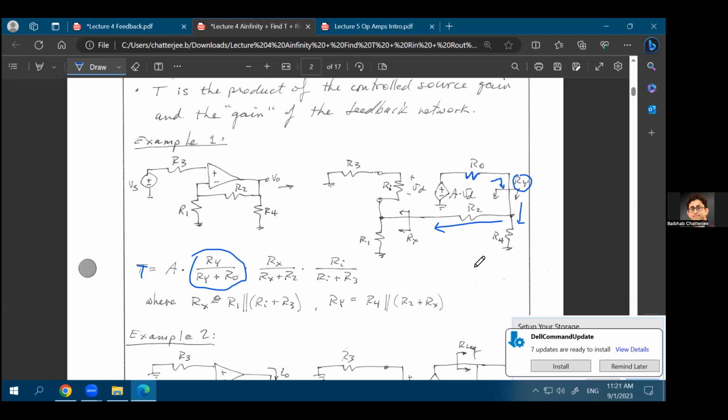No, right? You have two parallel resistances. The voltage does not get divided between the two. Voltage is the same. Current can get divided between two parallel resistances, but voltages are the same. So you will not even have to consider this R4. You just go on in your merry way to this left-hand side through R2 and then through these resistances.